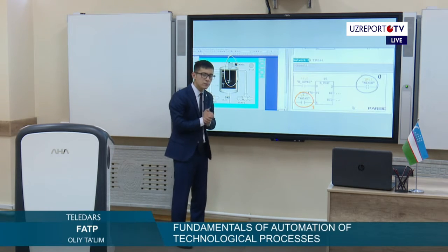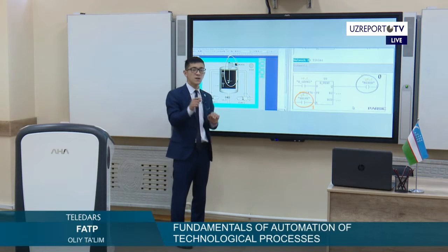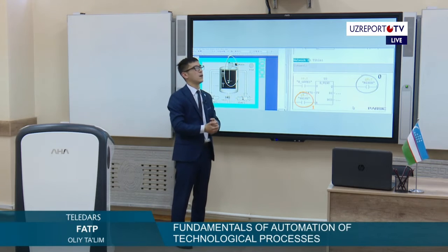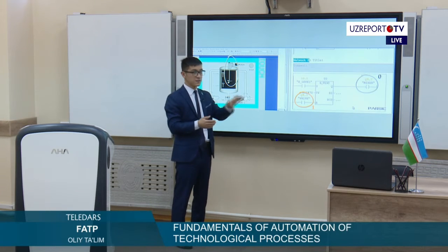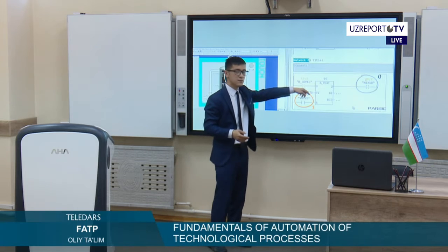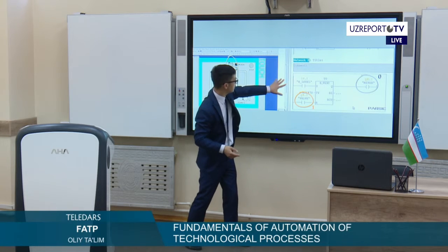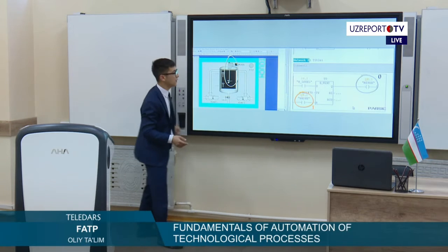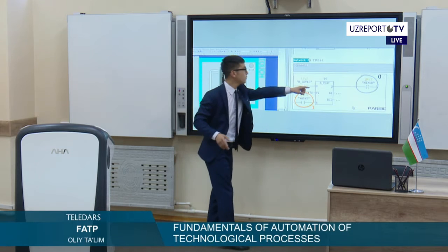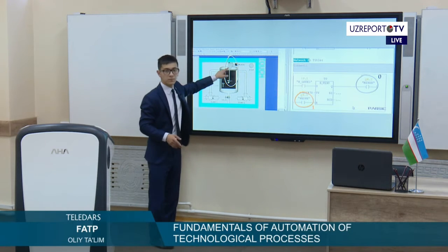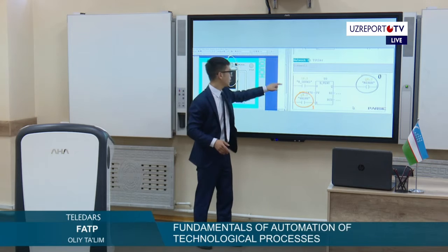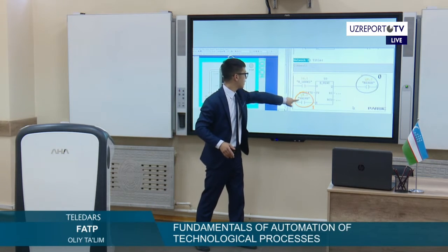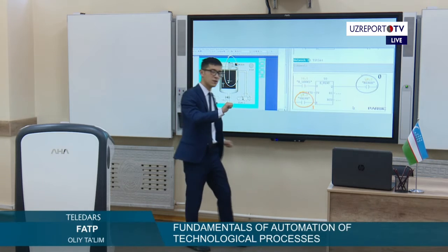Here, as I told you, if you can remember, the mixer will work 7 seconds. So it has a start and set and reset and time. So it will be a block with the two types of set reset with the time value, and you just put the 7, and for output give the mixer. As a result, after 7 seconds, it starts to work. Until this process, the valve will be off.